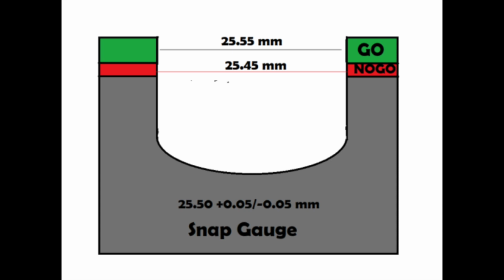You must state how you will ensure high quality in this process. The best work for this aspect references measuring equipment, tolerances, use of go or no-go gauges, dry fit assembly, jigs, and templates where the same components are required multiple times. Here's an example of a go, no-go gauge, and you can see on this that you would definitely want to stay within that go zone, and whatever process you're doing, you would want to stay out of the no-go zone.